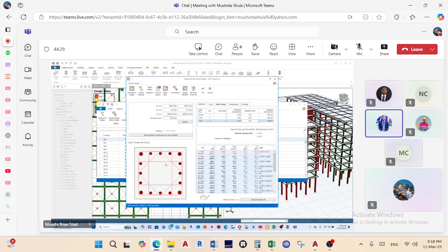So, to me personally, it makes sense. You have this column active over 8 stories. It's 450 by 450. I think you need a bigger column than this. I think people that have been to the King's Hospital may agree with me. We actually had columns as large as, was that 600 by 600? The ones that were in the bottom.